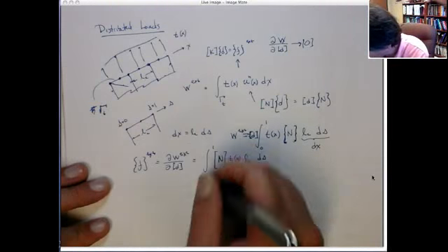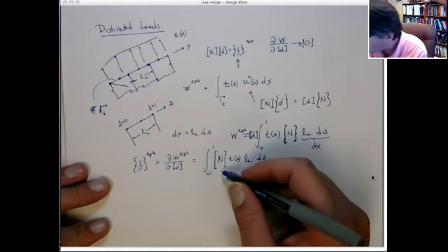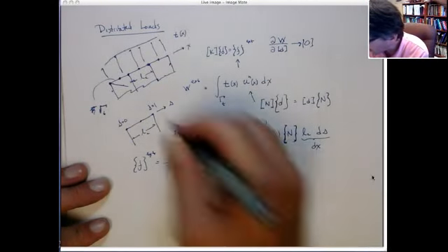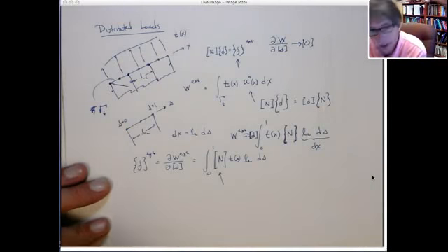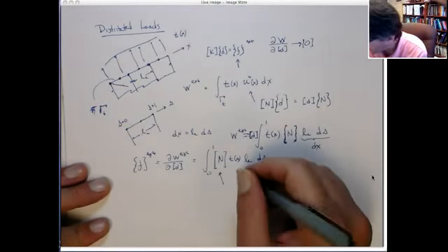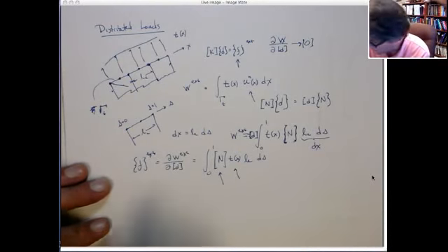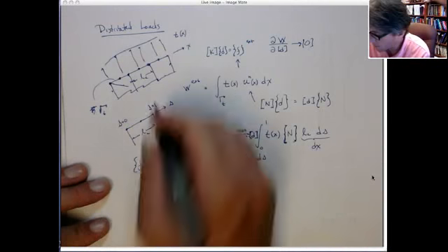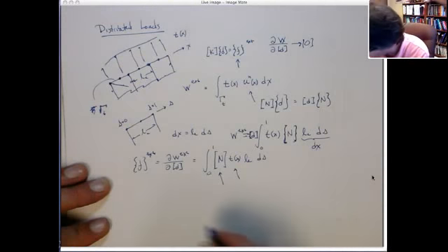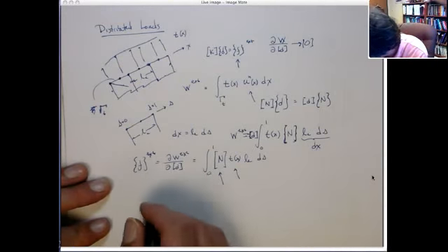So this is the equation, okay? You can use any element you want, put in the shape functions on that edge, and then for any given traction, you can then compute the external forces. And these would be nodal values that you then would apply on the nodes, okay? So let's do a real simple example. Let me just rewrite this.